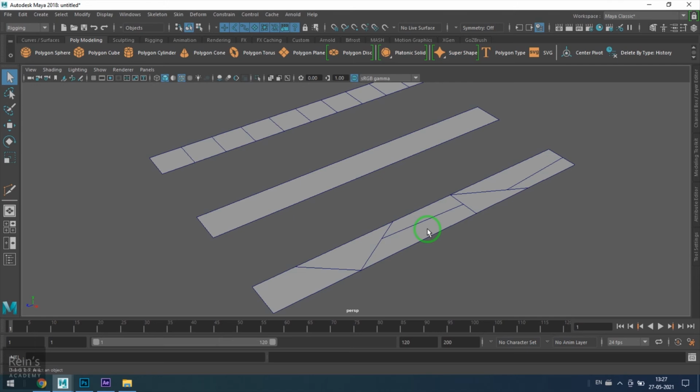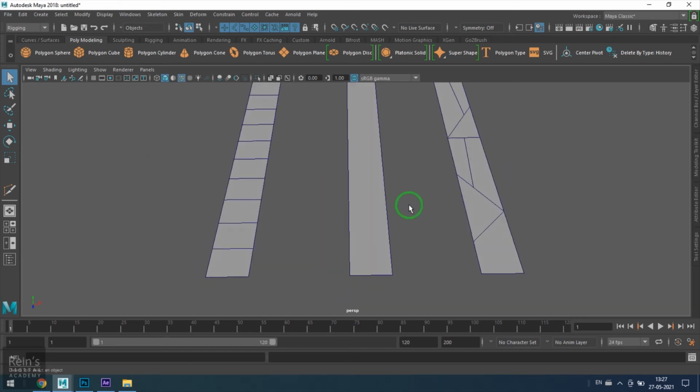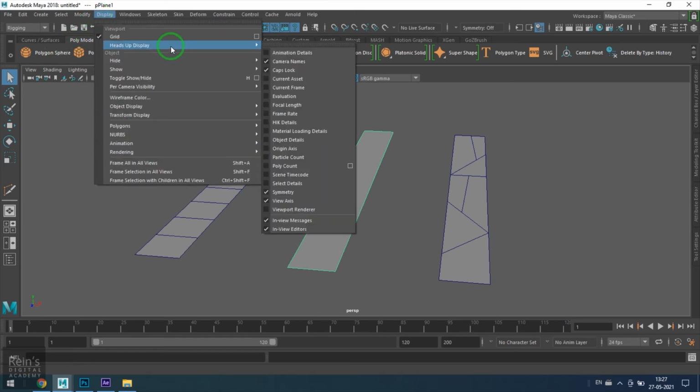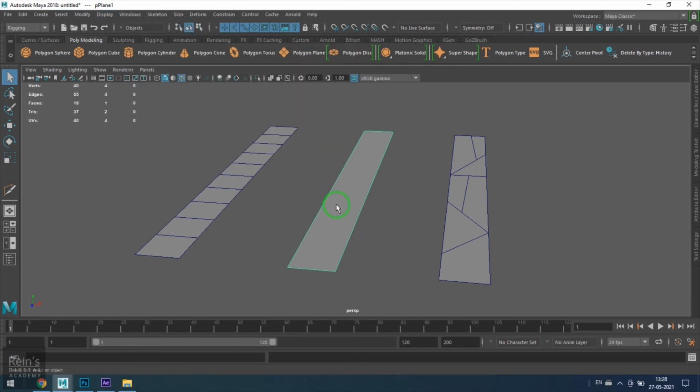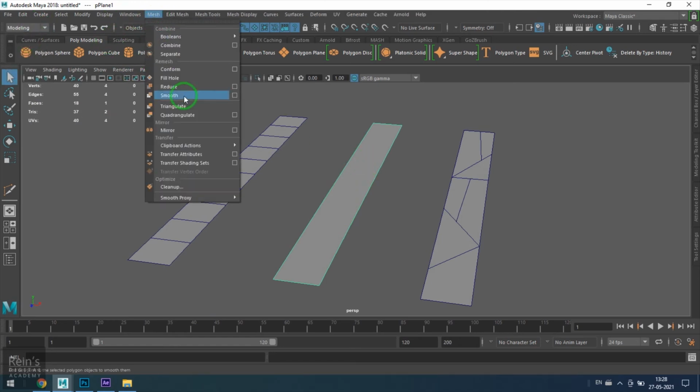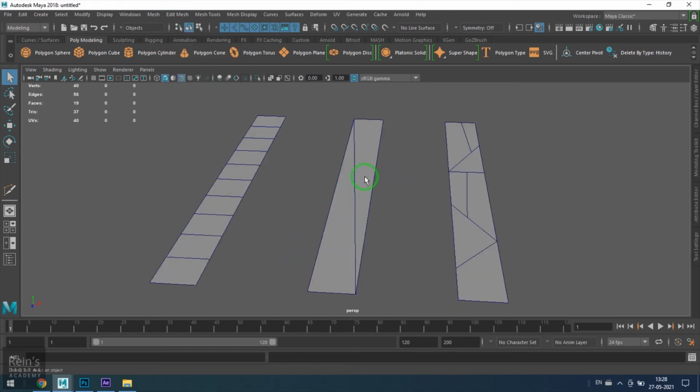deforming. You can use triangles because if you see right now this model, the polygon count, if I say it has one polygon, but it has two triangles too. I go to the heads up display, polygon count, and then if I select the model, this is the selected model's component count. So twice you have two here. So you might be thinking, where is the triangle here? But actually there are triangles. So these are the two triangles in the model.